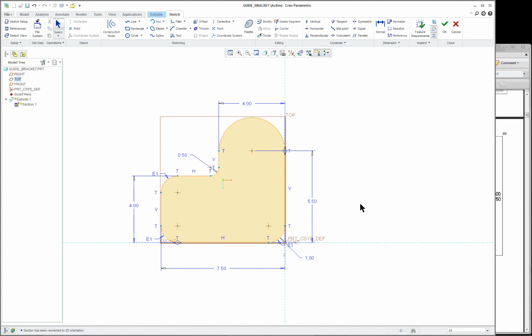The drawing dimensions are going to display what the model dimensions are, and those dimensions don't have to be moved if you put them in a nice position in the very beginning. You might have to move a little bit or clean up the dimensions in the drawing. But if you move them off the face of the object, which they're supposed to be anyway, it makes it a little bit cleaner when you get to the drawing mode and you're doing your documentation.